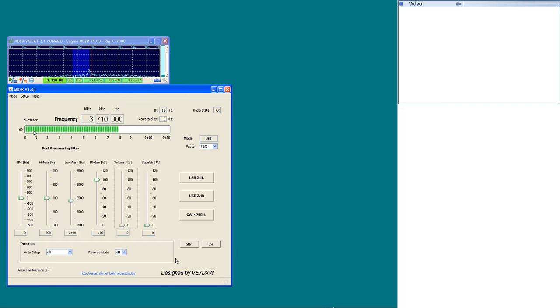Here is a functional description of the features of the MDSR-SA. The Run Pause button allows the spectrum analyzer to be stopped. If the processing time is needed to run other applications, the spectrum analyzer can be paused without having to close it. The Record Start Stop button records the audio from the sound card and stores it in a file that is date and time stamped.